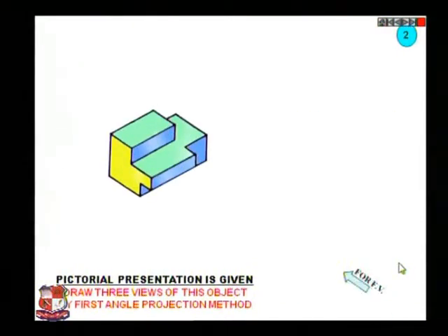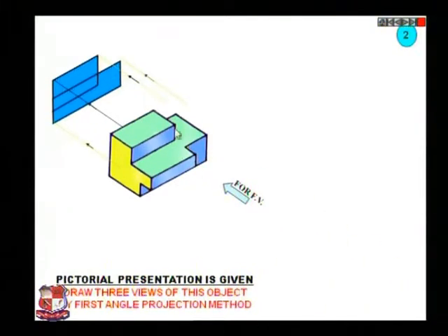Now second problem, this is the case, this problem is there. Now how to draw its various views? So for that, if you look from the front side, if you look from here, this blue colored portion would be visible to us, which is to be drawn like this. If we take projection from here, or if we draw lines from infinite distance from these corners, it would appear as shown over here. This rectangle, and this rectangle, right? Now about its projection, so this is the front view.